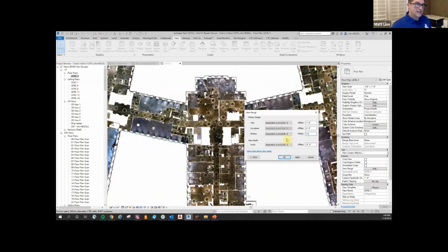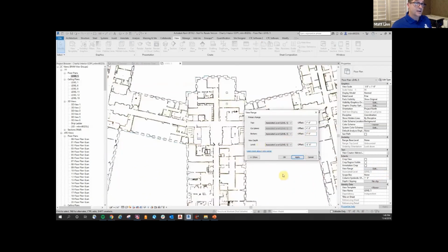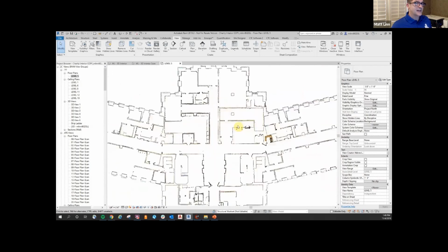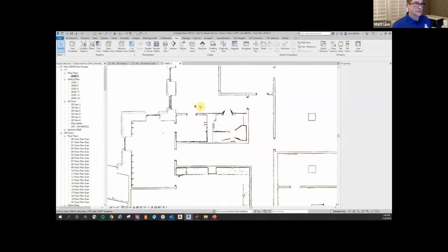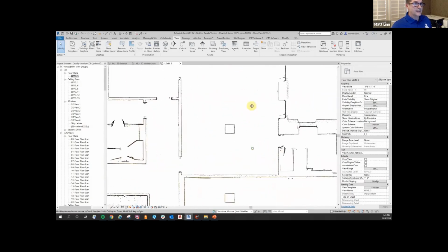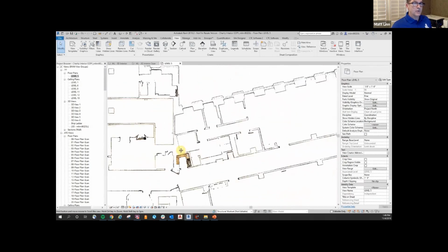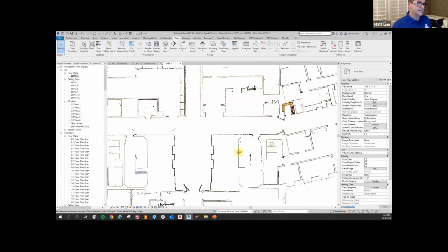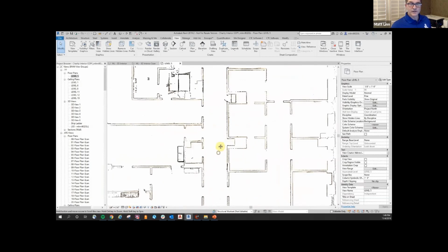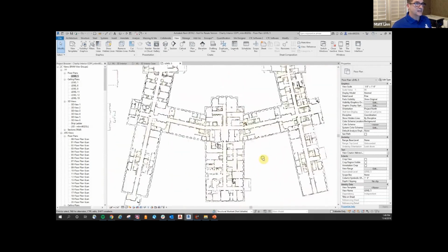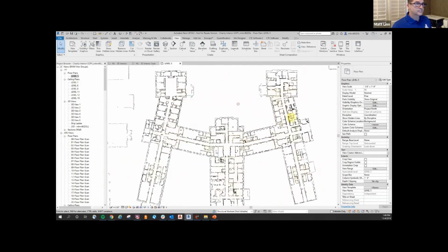Okay, similarly, if I bring it up to 3'6", that's the bottom again, and I'm cutting at 4. So similar to what James showed earlier, this is a slice through the plan, and it really starts to look like a floor plan. It starts to look like a drawing. Now again, this is in RGB mode, thus everything is the actual color. You can see casework here because that is between that 3'6" and 4 feet. Again, it starts to look exactly like a floor plan.